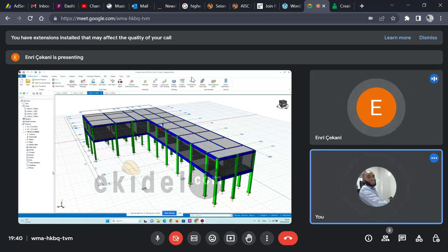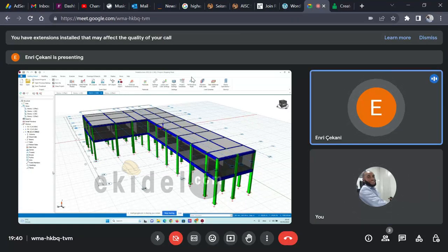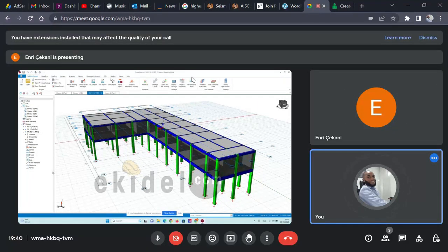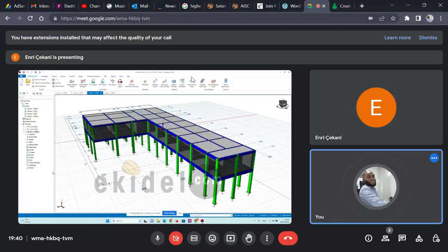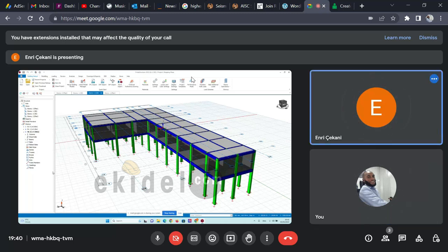This particular reinforcement only braces the joints, the joint between the column and the beam or between the wall and the beam. So they brace the stirrups in the critical zone with this diagonal reinforcement. And this is done on the sides of the beam. Okay, I got it.